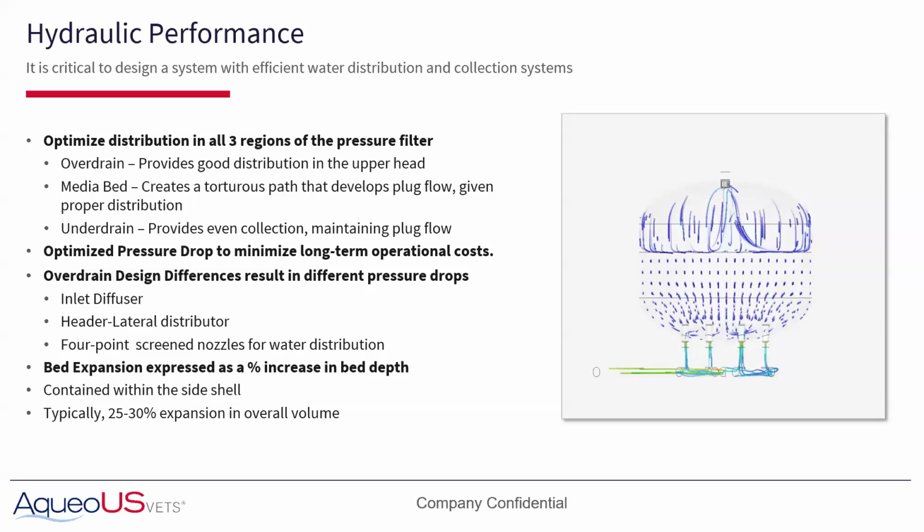Now it's extremely important for a couple reasons. One, from an activated carbon standpoint, the mass transfer zone, where absorption takes place, is very long for PFAS. So we can't be wasting a foot of carbon bed as a distributor. When you get into the ion exchange resins, these are round beads. They're all the same size and shape. If you have flow going in one particular place, it will actually push the beads up to the side. We do have pictures, not in this presentation, of the inside of a vessel where all the beads are pushed up to the side of the vessel.